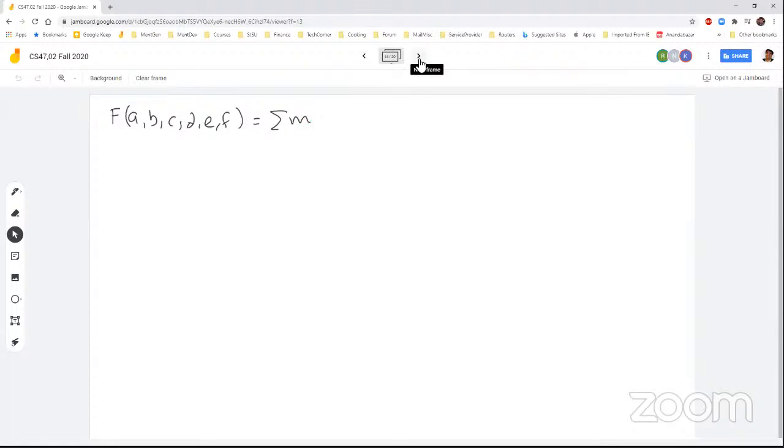A, B, C, D, E, F. Yeah, a 6 variable function, which means it will have 64 different combinations of the input. Like in the truth table, you will have 64 rows. So let's say this function is defined at 0 to 14, 31, 54, 59, for example, right? And you want to build that logic circuit.